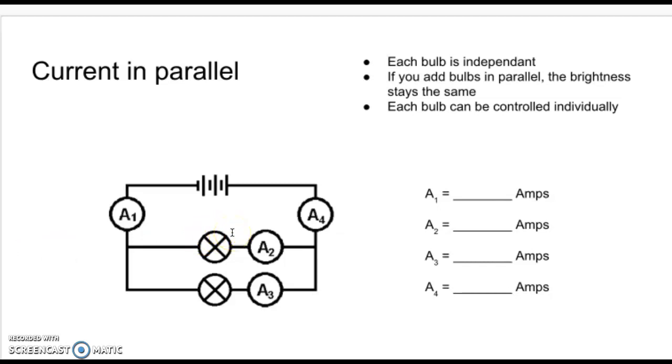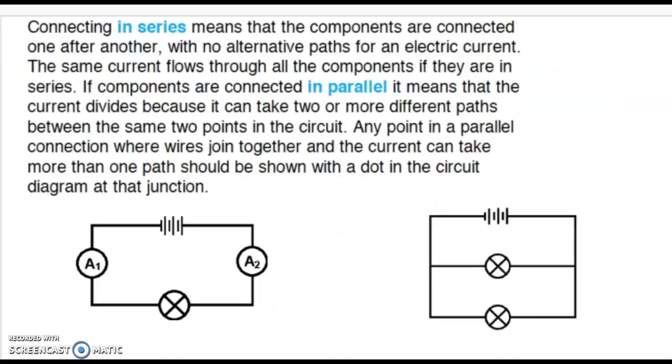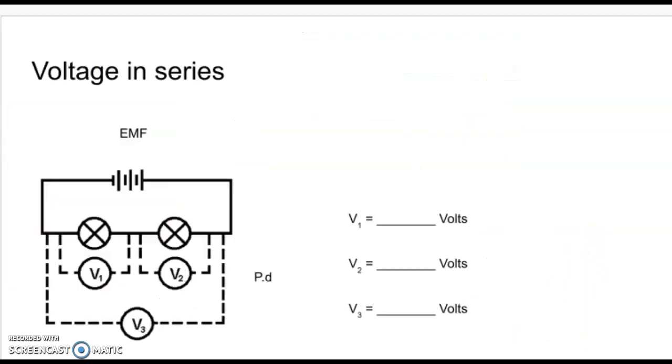Build initially without an ammeter, just build a parallel circuit, a circuit which is represented by this. Careful with your parallel connection. How are you going to do this? Now, once you have that set up, you can try your ammeter in 3 different positions, or 4 even. You can put your ammeter here before the branch. Then you're going to look at what's happening after the branch here and here. And then you're going to see what happens after the 2 branches come together in your position 4.